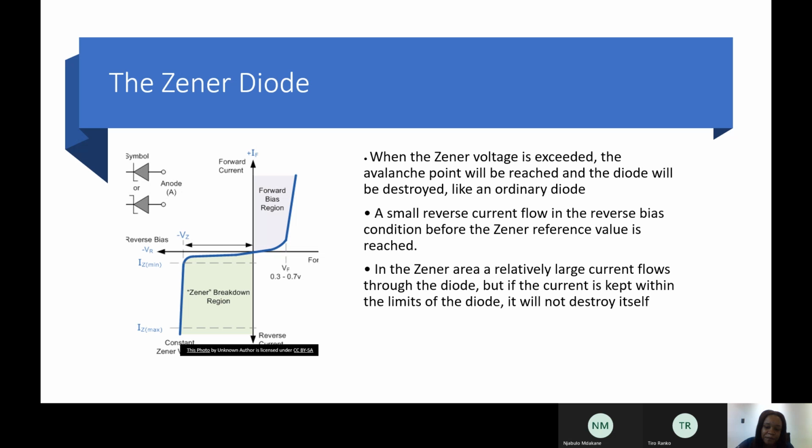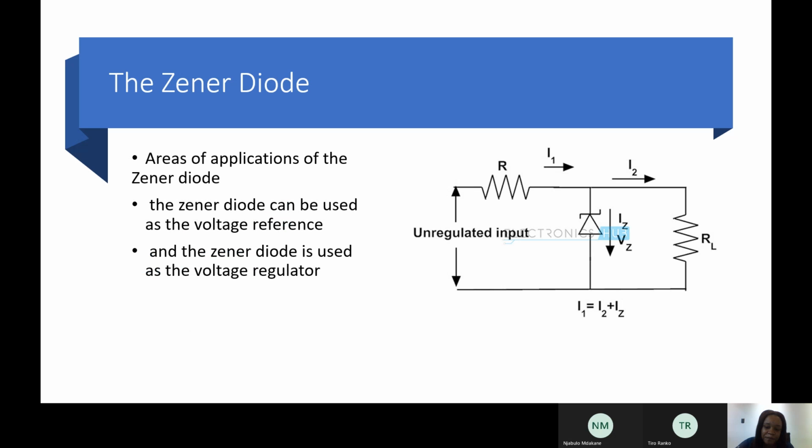Now, the other thing about the Zener diode is its application, which is one thing you should know. The Zener diode is basically used as a reference. It's used to regulate voltage. It's a regulator. You didn't do so much of this in the power supply, but it cuts down voltage and makes it into a direct value.